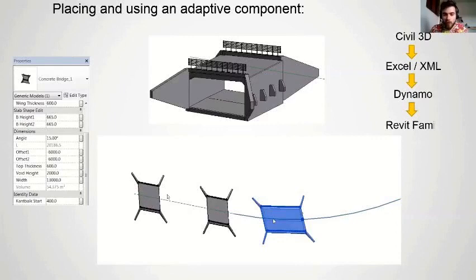And we also had a location curve, alignment as I believe is the correct term. And that alignment was spread over tens of kilometers. So we had coordinates on that alignment, and these were just 1D coordinates. What does that mean? It's a number that tells you at what distance from the beginning of that alignment curve you place the bridge.